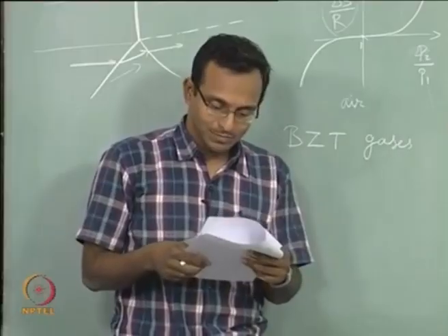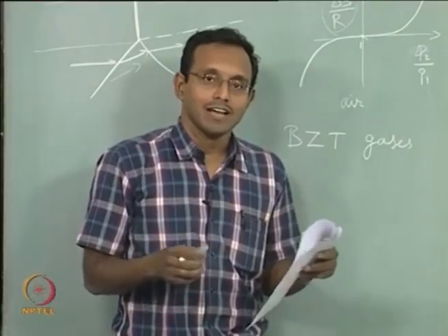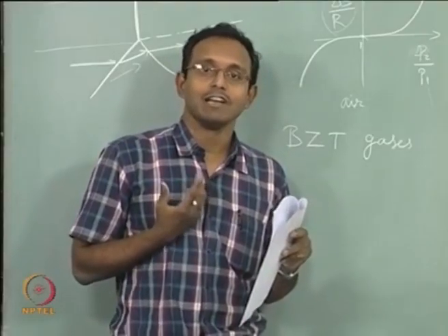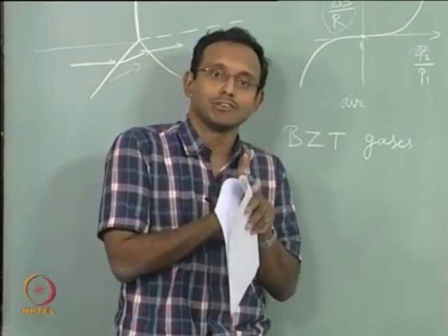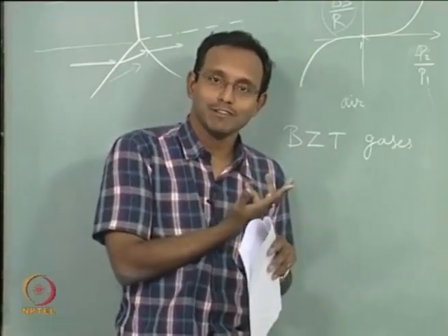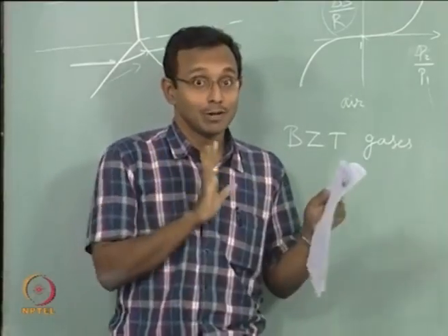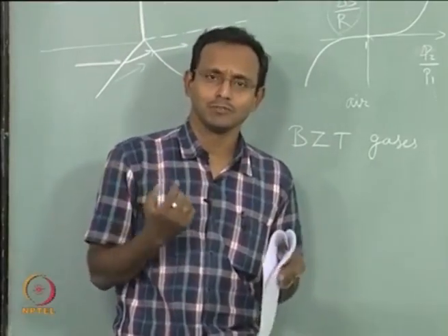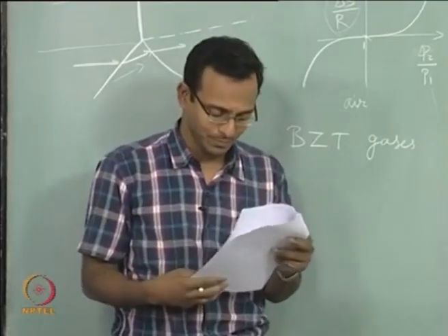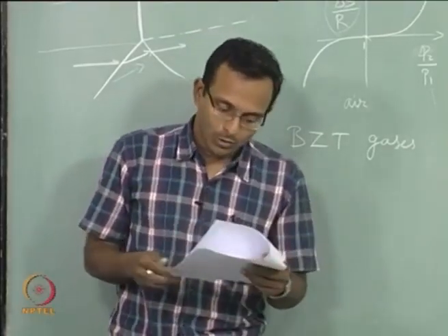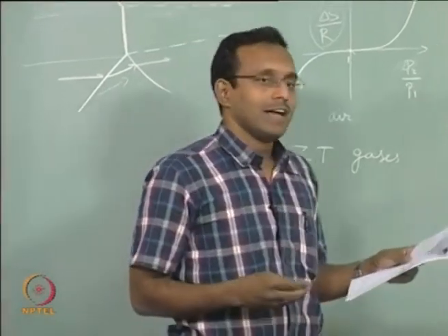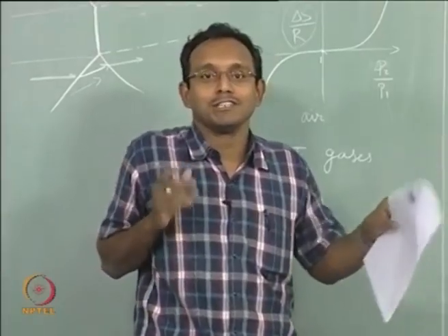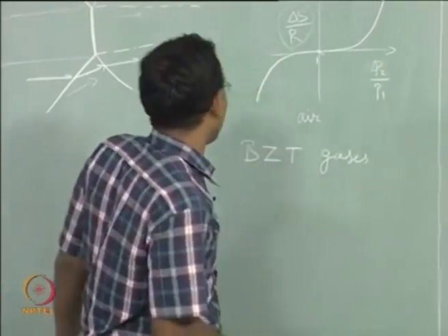So now the way to think about it, I will have a set of expansion waves, let us say, in my flow. They will not coalesce to form an expansion shock, but if I send a whole bunch of compression waves into my flow, they will all coalesce together to form one thin layer called a compression shock, which is what we have been doing all this time, normal shock, let us say. So the way to look at it, I am going to consider expansion as happening over a big region in the flow. What is a typical example for an expansion?